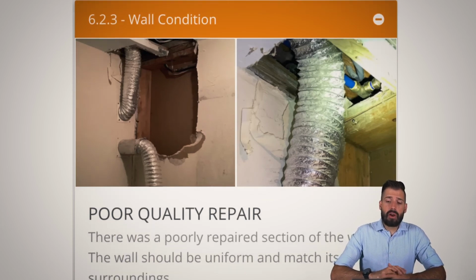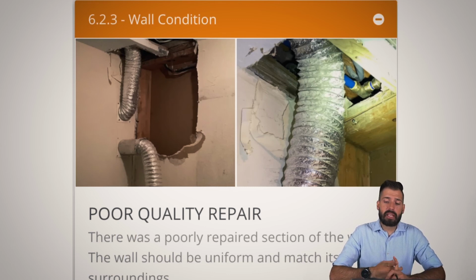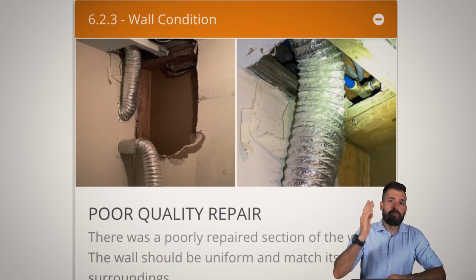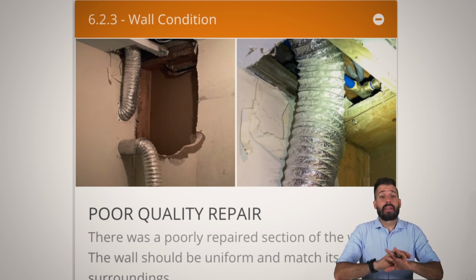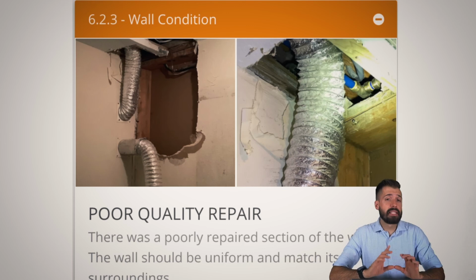So if there was a repair, why is there a repair? Well, it looks as if there was a leak because you can see in the picture directly above me, there is some brand new PEX pipe with SharkBite fittings. Now, I have nothing against SharkBite fittings. They are really, really good, but I'll tell you what, it's not necessarily the most professional repair. It almost seems like a homeowner repair, but sometimes SharkBite is the only viable option because of being able to fit tools and costs and expense.